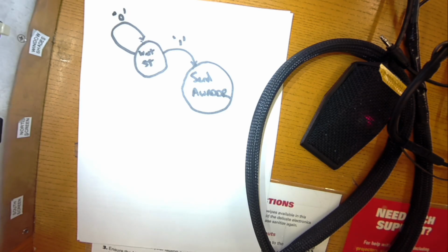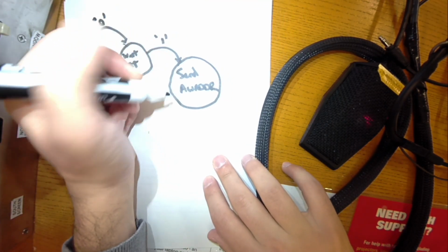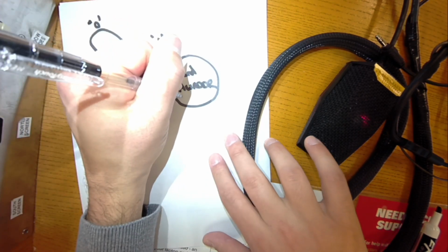And then you would have a second process. That second process I typically do as a purely combinational process with no clock at all. So you have to watch out for sensitivity lists and the like. That process would be sensitive to the current state as well as to the inputs. And that would determine what my output should be based on the state that I am currently in. That allows me to write my state machines, and I'm literally running out of space already here, but to be able to say things like, I'm at this state called send AW address, and I know what I need to do, right? I need to actually send that signal or set that signal.